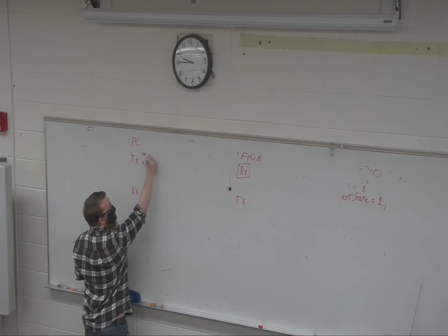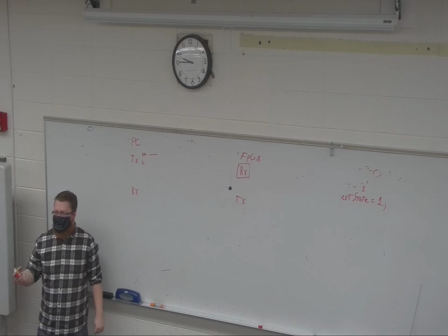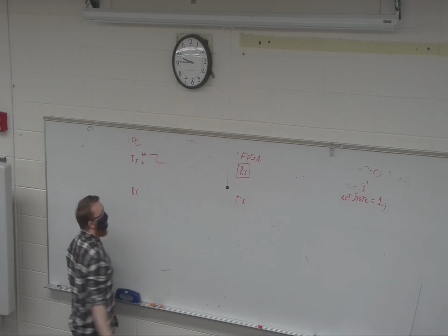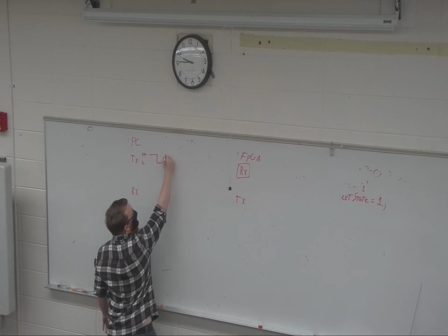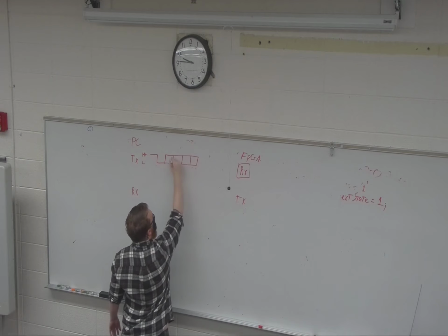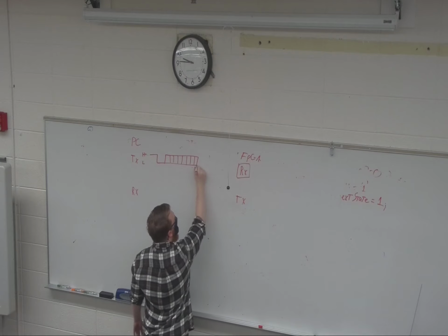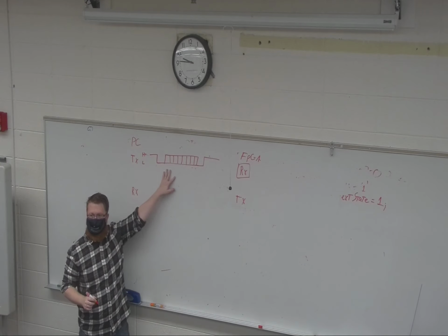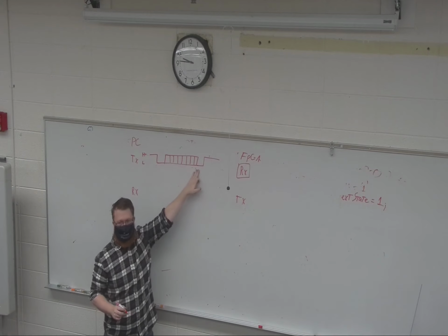The way this works is the line sits high to let it know it's active and plugged in. When it wants to start communicating, it has what we call a start bit, where it drops low for 1 bit cycle. And that says, I'm about to send you data. Then it sends a block of data of 8 bits. So this is the UART standard: start bit, data bits, stop bit.